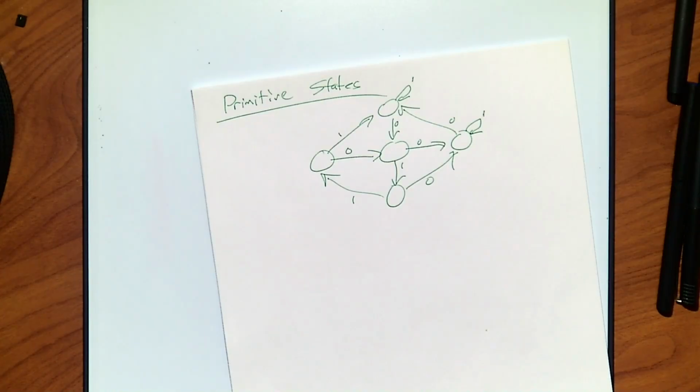How do they do outputs? Anybody remember what outputs are stressed on these states? We put a slash in. Right? Now the question is, where do I put the slashes? I can put them in the states. I can put them on the transition areas. You can't do both. One or the other. That's just the rules. Okay? And the reason for those rules is it keeps it more systematic. There's some design rules to them.